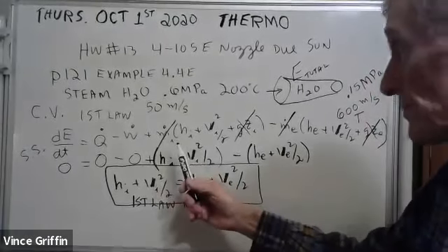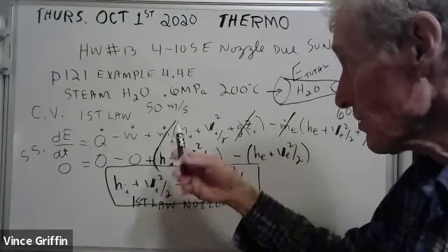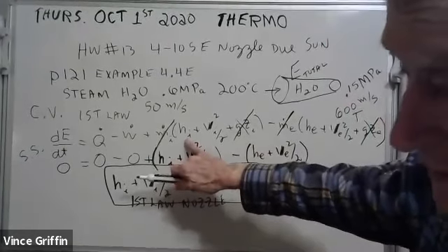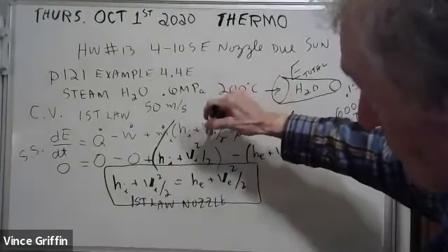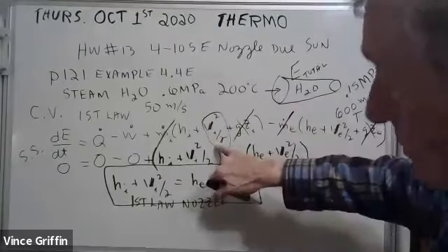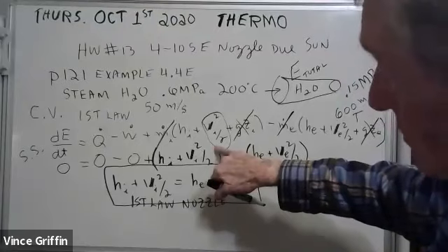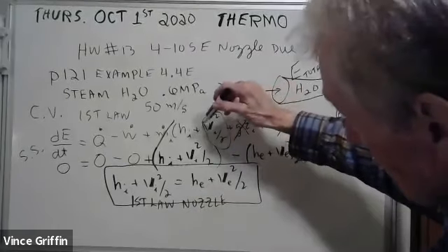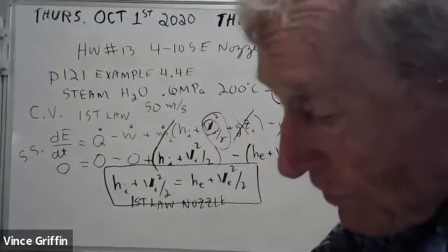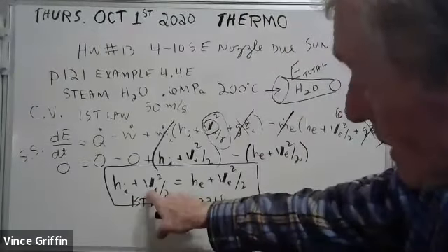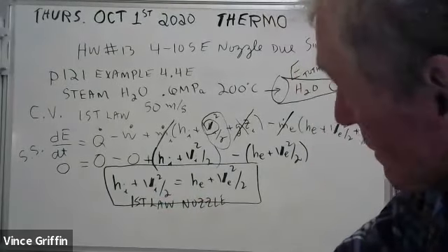We talked about the different terms. I didn't tell you what that was. That's got a name. It's called the incoming specific enthalpy. This whole term here is called the incoming specific kinetic energy. That V there, if you're just looking at that V sub I, that's the incoming velocity. See that V sub I? That's the incoming velocity of the steam coming into the nozzle.